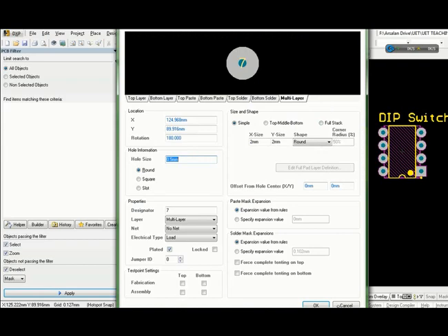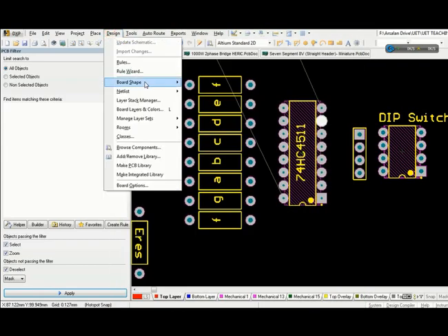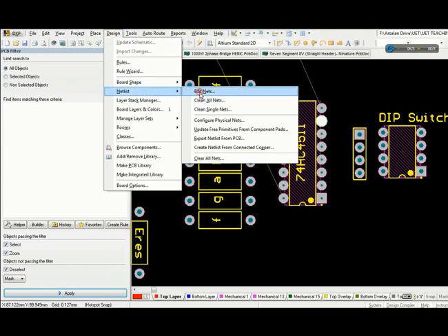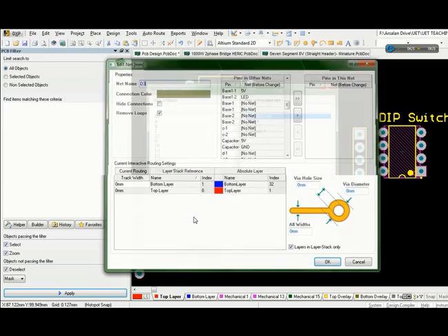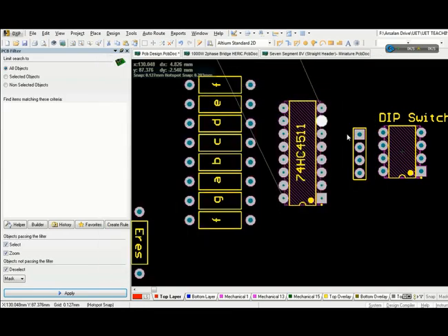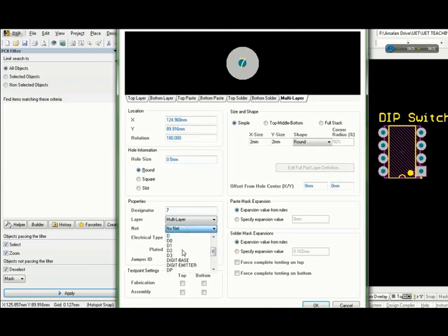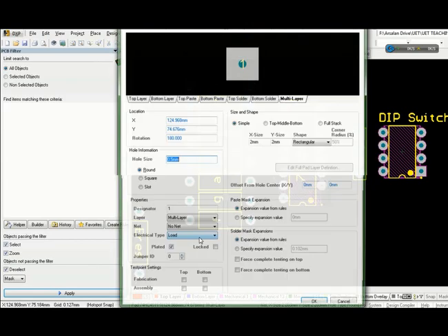Now you can see I'm pointing D0, D1. In fact, I have missed some nets actually, so I'm going to make those nets as D0. Please either use small letters or capital letters. Don't make it a mix of both, because otherwise it becomes difficult. But if you can handle it, it's as such no limitations.